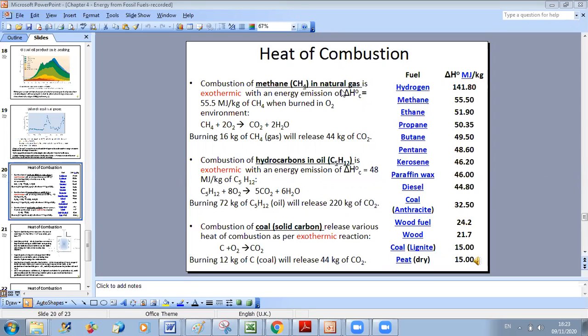If you take a course on combustion engines, you will study complete and incomplete combustion. Even if it's incomplete, we use a coefficient of excess of air that is not very small, minimum 0.8. What I mean by this is we should provide more than 80% of the required air, because if we reduce the air a lot, then we will have a lot of monoxide of carbon, which is very harmful to the environment.